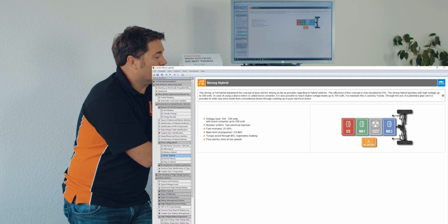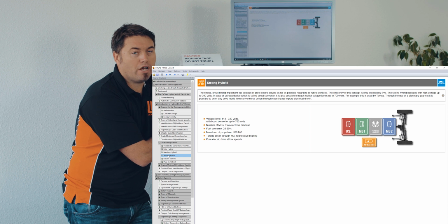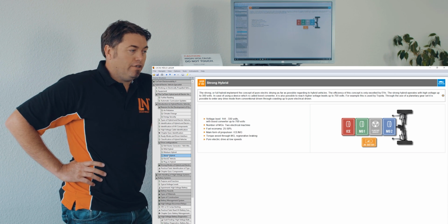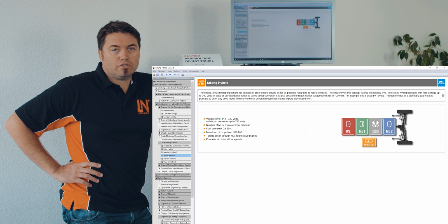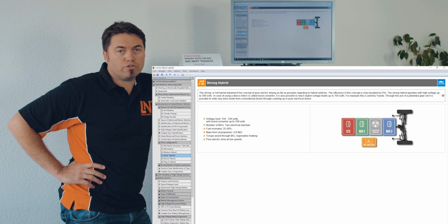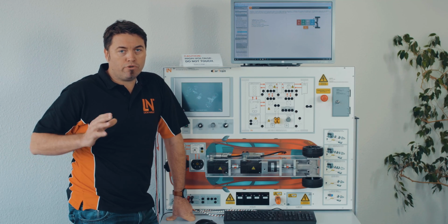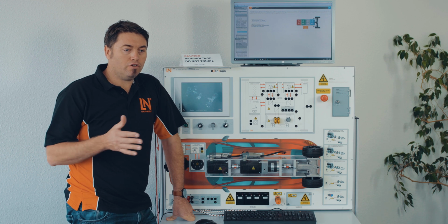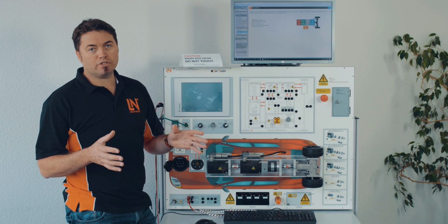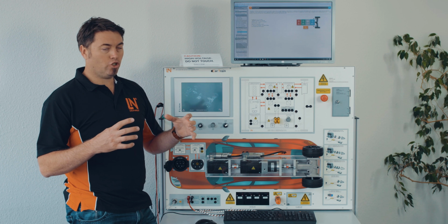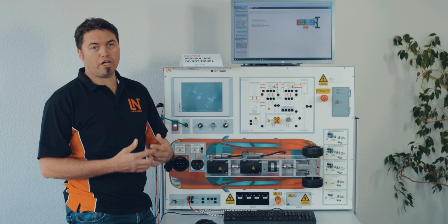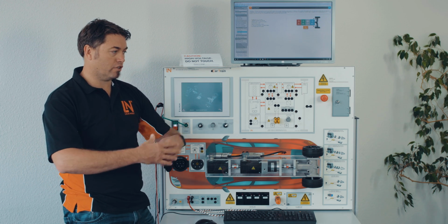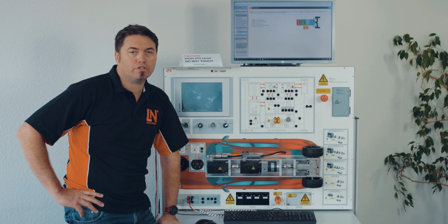So what's quite surprising about the Prius is you're only going to get up to 2 kilometers to 5 kilometers, so 2 miles to 4 miles range on pure electric mode. It's not really designed for driving in electric mode. It's designed for having the battery. The battery is then basically an accumulator which absorbs the energy from regenerative braking. That's basically the whole idea behind the Prius. It's not for driving for hundreds of miles on electric drive.